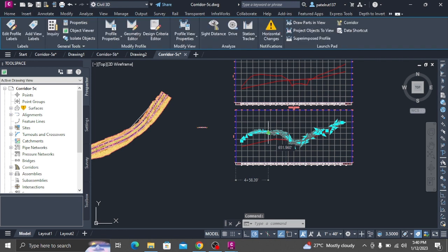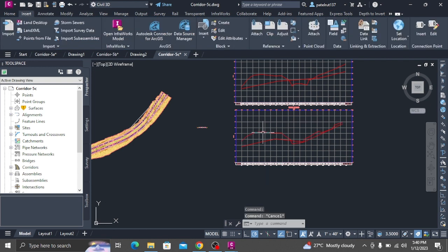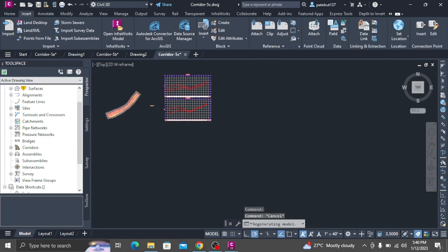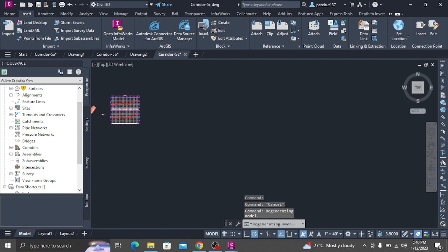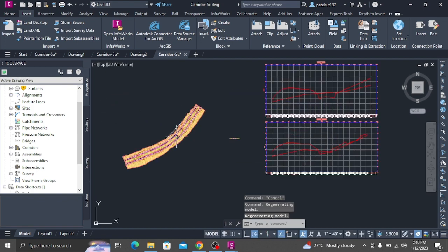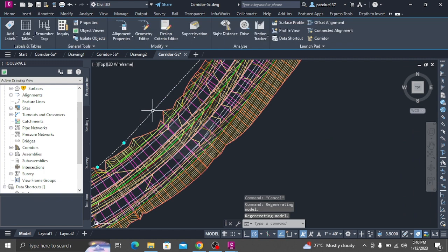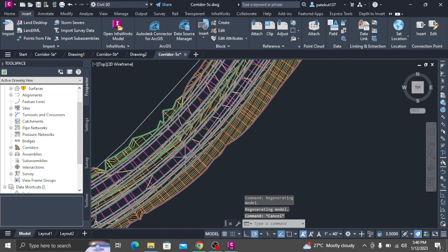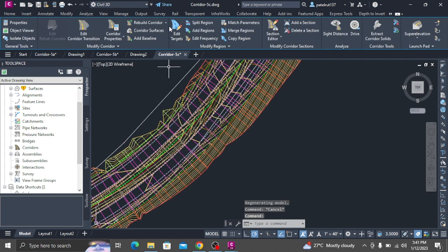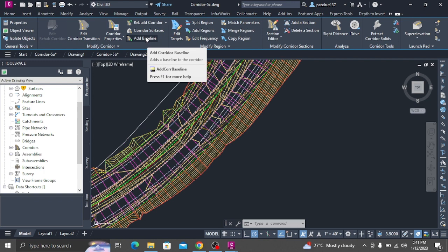Click OK. The Hide Surface style has all of its components turned off, which allows the surface's render material to be effectively ignored. The rendering method used in this exercise applies render materials that are assigned to the subassembly link codes, and not the surface itself. Follow steps 2 and 3 to apply the Hide Surface style to the Corridor 1, Pave and Corridor 1, Top surfaces. Note: the Corridor 1, Datum surface already uses the Hide Surface style.